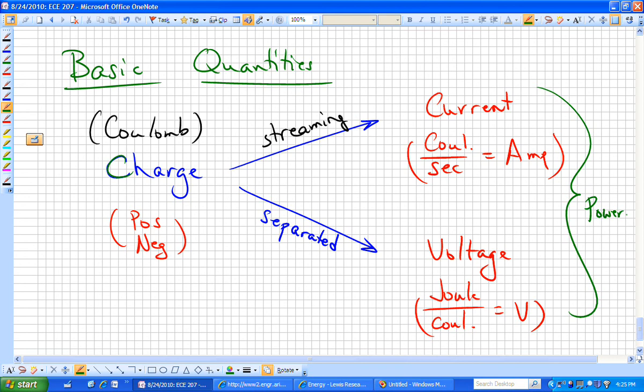It might have a battery. That battery is so many volts, and then it consumes so much current per unit time. And you might look on the battery, and it might say 800 milliamp hours, and that would tell you how much energy is stored in that fully charged battery. You're assuming it's so many volts, maybe 3.7 volts. Your ability to make technology so that you can store energy in a smaller and smaller place allows us to shrink and shrink all these cell phones.